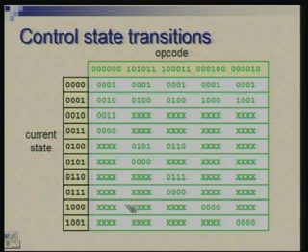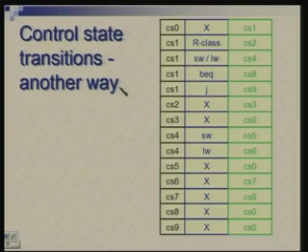So now it describes a truth table with a group of 4 inputs here and a group of 6 inputs there. So this table is defining 4 outputs, and there are 4 plus 6, that is 10, inputs. So we can have it implemented by a PLA, but before that I am showing another way of looking at it.